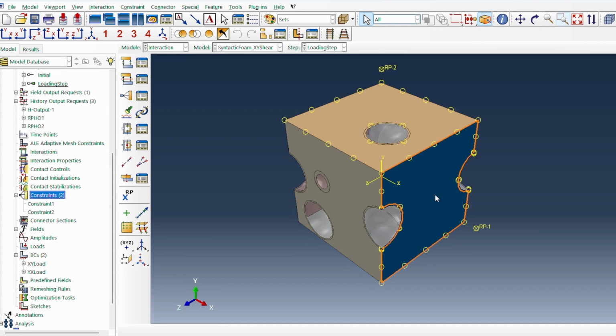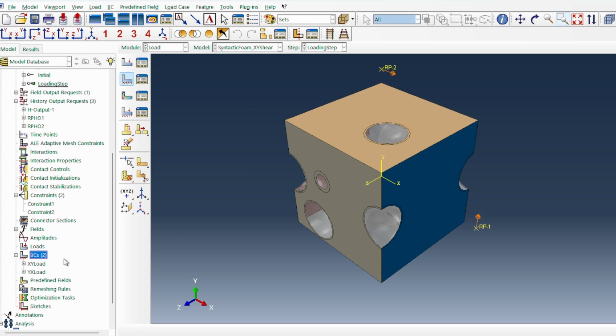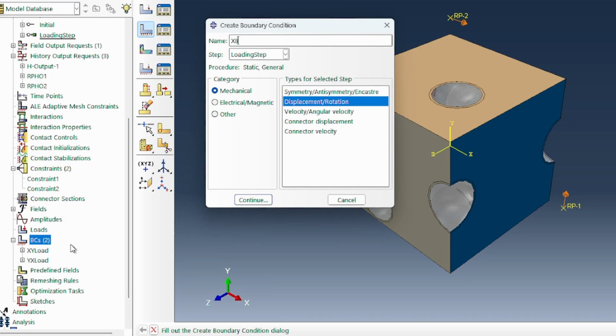The other thing is that we need just 2 types of boundary conditions. Because we are working on the XY plane, our boundary condition would have to be an X back boundary, because we are applying the load on the front, and the back will have to be fixed.